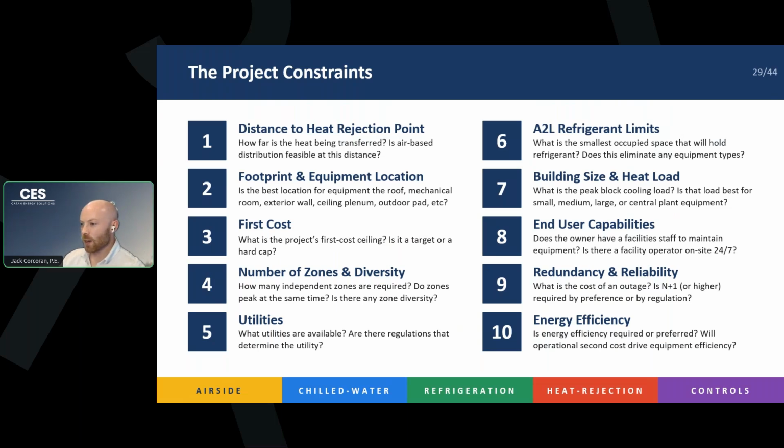As I said, if it's a single room that is a perimeter room, you could just open a window. That would be the best, easiest solution. But we all know that living in New York, we have to be able to transfer that heat in the summer and use cooling. So a PTAC might work great for a single perimeter room, but if you have an interior room or something's located in a basement, you have to figure out some way to get that heat somewhere else. So, ductwork, refrigerant, chilled water, condenser water, those might force you to use extra loops if you have to transfer that heat a long distance.